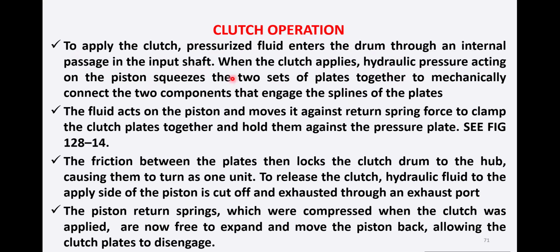So the multiple plate clutch operation is like this. To apply the clutch, pressurized fluid enters the clutch drum through internal passages in the input shaft, from which the power is coming. When the clutch applies, hydraulic pressure acting on the piston squeezes the two sets of plates together to mechanically connect the two components that engage the splines of the plates.